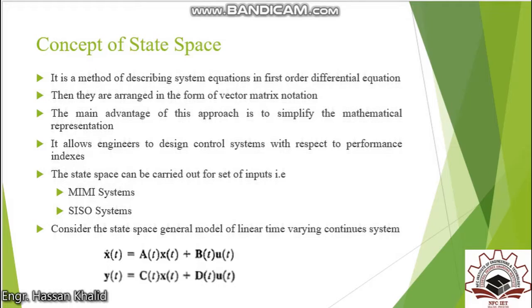The main advantage of using this approach is to simplify the mathematical representation. The users have direct access to the input states as well as the output states. It also allows the engineers to design the control system with respect to predefined performance. The state space can be carried out for a set of inputs. Either the system can be MIMO, which is multi-input and multi-output, or it can be SISO, having only a single input